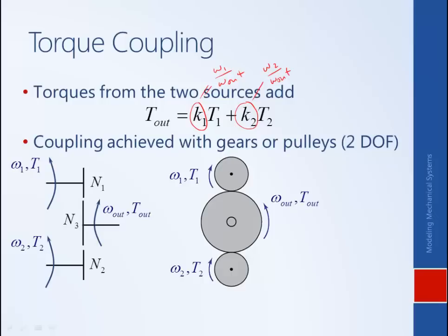This kind of device we define as having 2 degrees of freedom. So that's what DOF is, degrees of freedom. And that comes from the fact that this relationship here, we have a single equation with 3 variables. And 3 variables minus 1 equation equals 2 degrees of freedom. And so what that means is, in essence, we can set the torque of the IC engine to be whatever we want, and we can set the torque of the electric motor to be whatever we want.